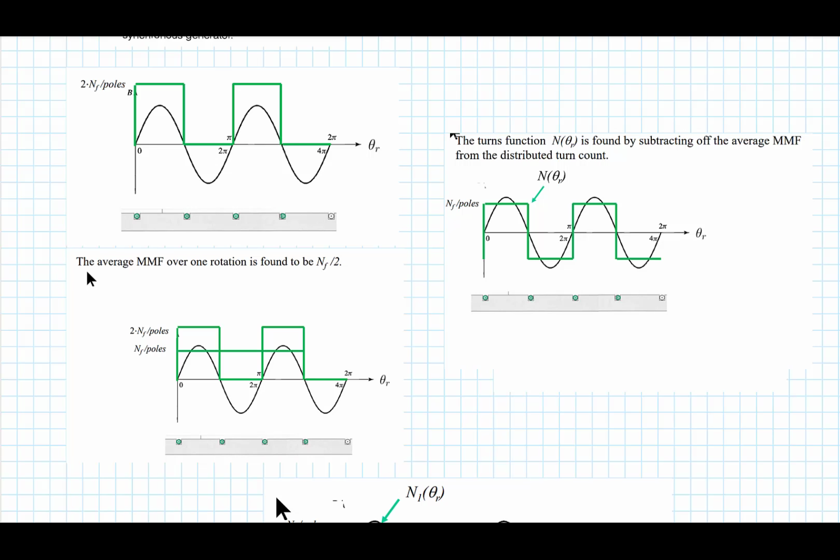What I want to do now is to analyze the magnetomotive force, or the MMF, that is going to be produced by the field winding. And that's the MMF that's behind the flux density that we were just discussing. Now, the way that we do this with a rotating machine is we look at the rotor, which is shown right here, and we kind of flatten it out, make it look like it's just this flat, rolled out thing. And we look at the current going into the coil, and we're going to look at this 4-pole machine.